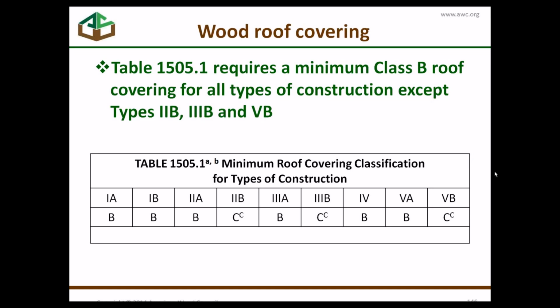In other words, if you're in perhaps a fire district where you have wildland fires, and you're maybe using Appendix D in the back of the International Building Code, then you're going to have some additional restrictions above and beyond these in accordance with the International Wildland Urban Interface Code. And it says so right in footnote 1 of this table. It alerts you to that.